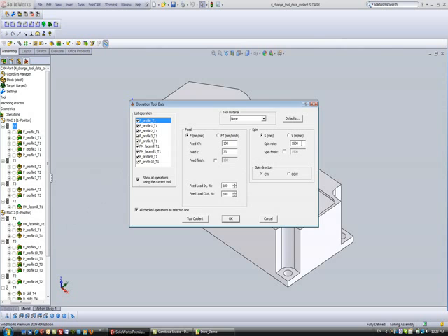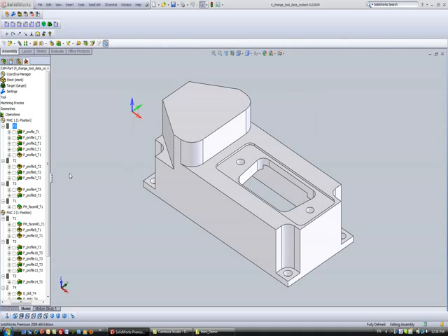If I want to change the tool data in every single one of those, simply do exactly as you see on my screen now, with all of them being marked, and change the value as needed. For instance, I can change my value here to 2000 and my feed to, say, 200. When I say OK, every single one of these operations was changed.